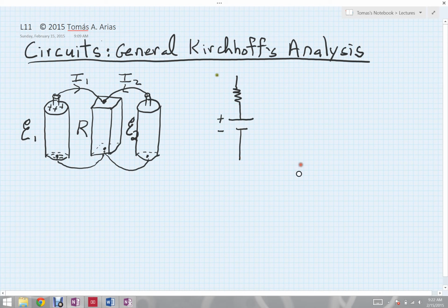So it is actually this unit here inside the dash box that represents the first battery, where we still have the ideal EMF E1, which gives us the voltage across the battery if there were no current flowing. And then this linear drop-off in potential that we lose, we can represent as a model, a resistance, an internal resistance this is called.